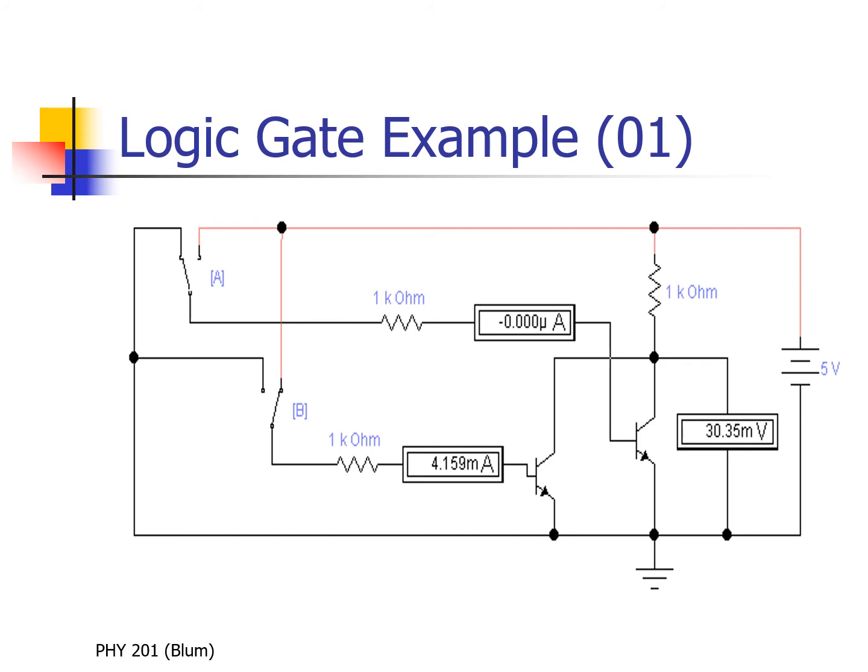The effect of a transistor being off is that it has effectively a very high resistance, and when the transistor is on, it has a very low resistance. So the resistor on the right has a high resistance, the transistor on the left has a very low resistance, and those resistors are effectively in parallel. And so if there's an easy path, because they're in parallel, the overall effect is easy. So those two transistors give a low resistance overall of the parallel combination.